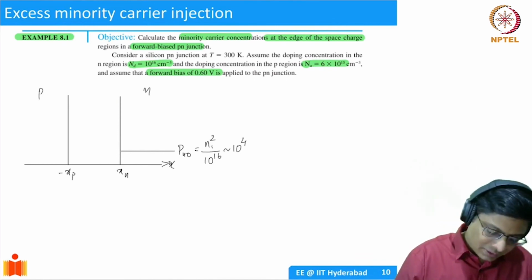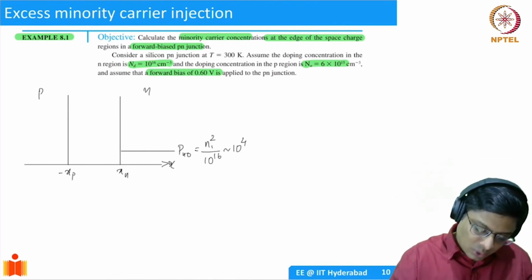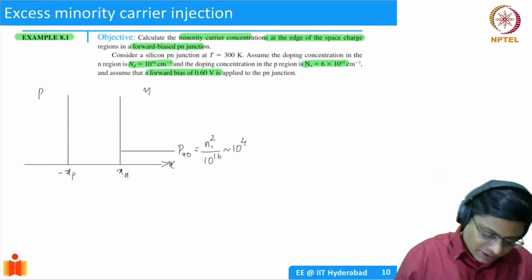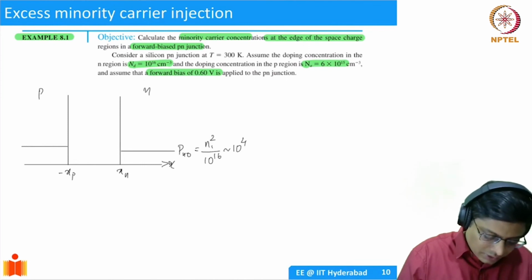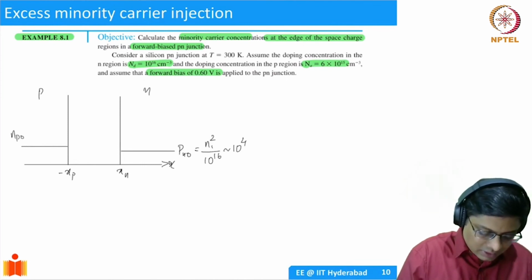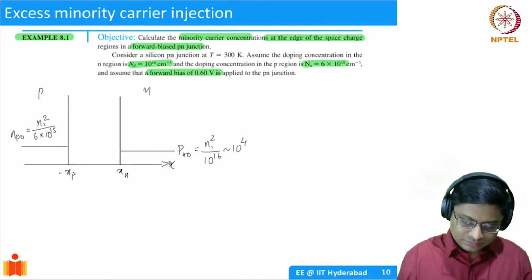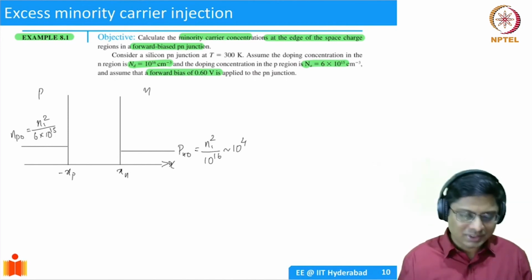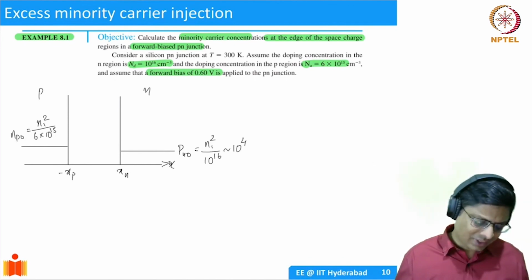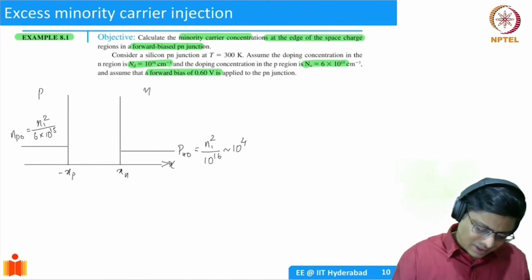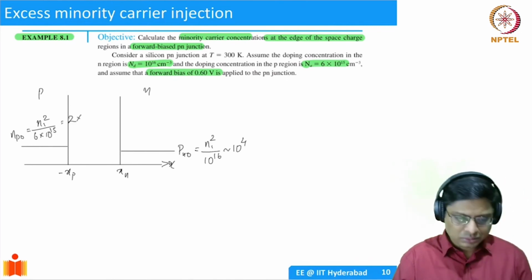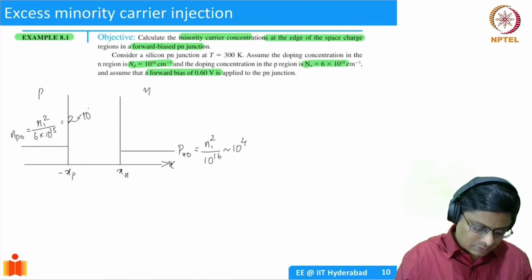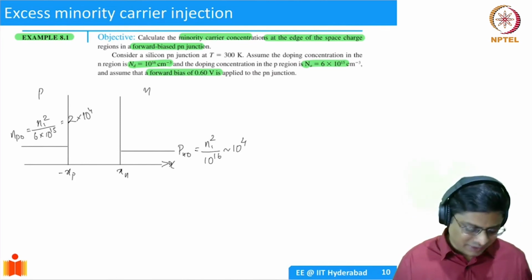What about the P-type semiconductor? P-type has a slightly lower doping density. So the minority carrier concentration is going to be slightly higher. So here I want Np0 equal to Ni squared divided by 6 into 10 power 15. Okay. So it will be some number you could just calculate. I'll take it as 5, so it will be 2. If I'm not wrong, it should be something like 2 into 10 power 4, maybe something like that. Okay. So please make sure that you verify these answers.